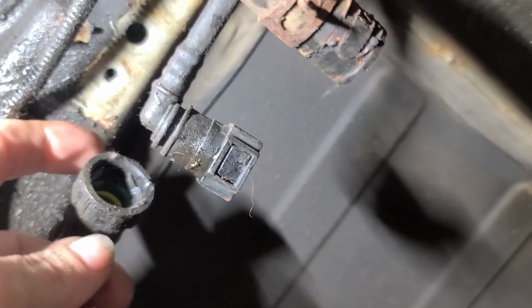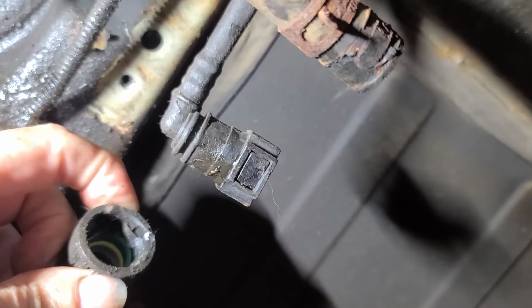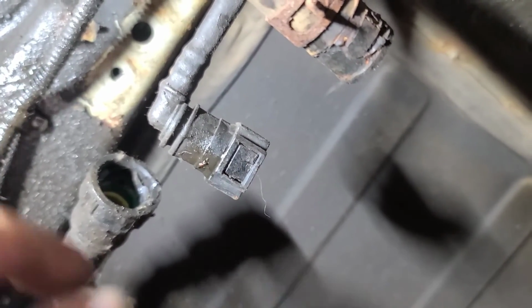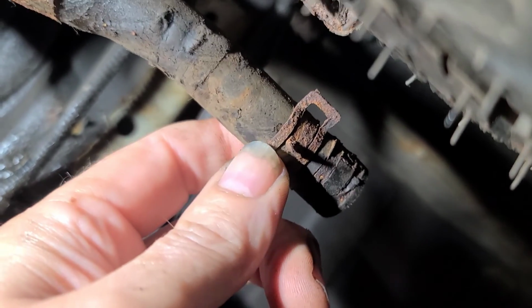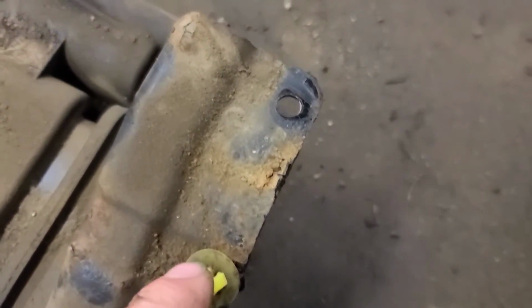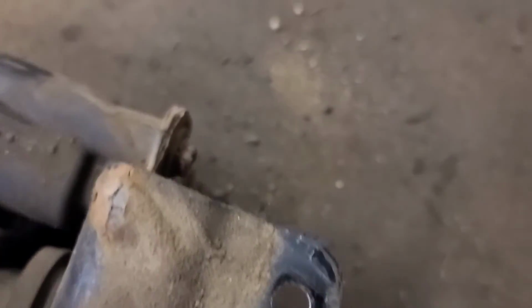Okay, so I got the charcoal canister off. Remove this hose by squeezing down on these 2 plastic tabs and pushing it that way. Remove this pipe by squeezing these 2 square blocks and pulling it off. This is a hose clamp, which I'm going to change. They're pretty rusty. Have a look at what I see here. I've got the charcoal canister off. Oh, there's 2 plastic clips that you have to pry out. They're kind of redundant, I guess, to hold it on until the technician puts the bolts in.